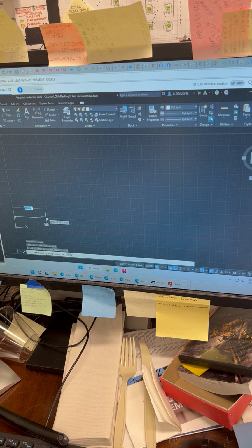You're using direct distance, and this direct angle is going to be at the 0-degree angle. You don't have to put any of that. That's the whole point. How convenient this is with the ortho. You just point your cursor in this direction. And I want everybody to put in here the distance of 36 units, just 36.